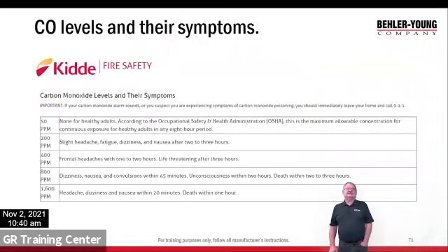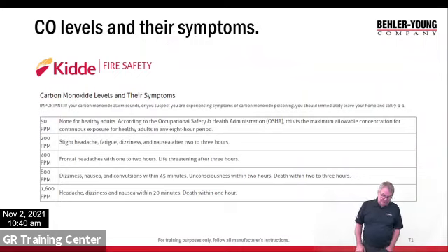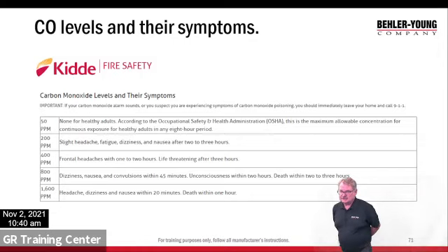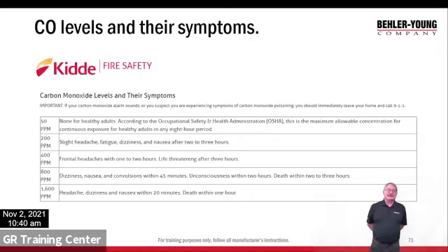Okay, so CO, if I look at this little chart, remember we had that CO detector I showed you earlier, and you can see right there, 50 parts per million. For healthy adults, you have to decide whether you're healthy or not, we're allowed to be in a room in that environment for an 8-hour period working, and it's not going to be harmful. Now look at 200 parts per million. Now think about that, a million, 200 millionths, 200 parts a million.